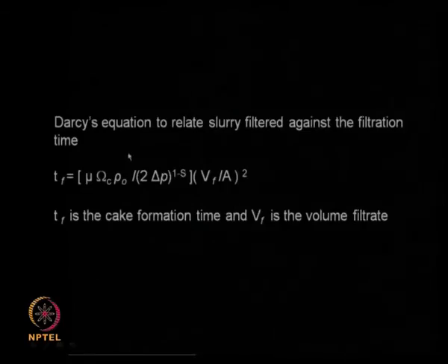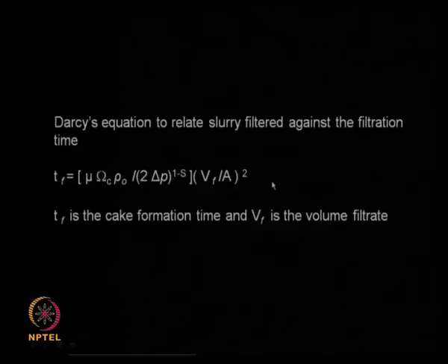So during the first stage, when the drum is inside the slurry tank, we can still use the Darcy's law relationship as we derived previously.